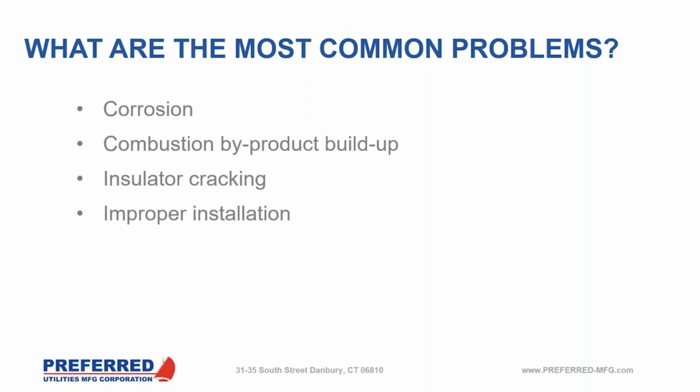Some will try to put more of the flame rod into the flame, and it actually will bring the flame signal down. So actually watching flame signal and making sure that it falls into the range that the flame safeguard manufacturer recommends is key to making sure this is operating properly. And a lot of times, if someone has some intermittent flame failures and it's a flame rod application, cleaning that flame rod or replacing that flame rod fixes the problem right off the bat.